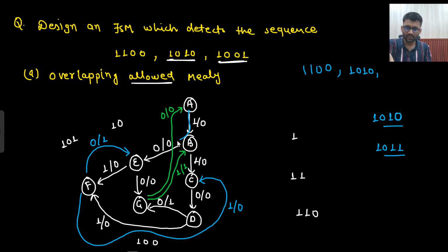You can see here 1 0 0 and 1. You see this cycle, 1 0 0 and 1. So if I am moving ahead in the states, that means my sequence is being detected. Finally, when the output becomes 1, at that time my complete sequence has been detected. So 3 times I can see 1, that means 3 sequences are being detected here.